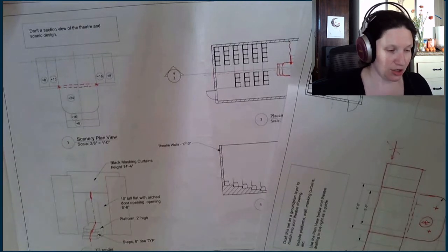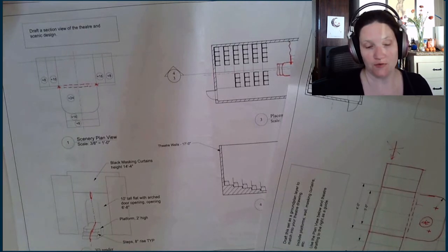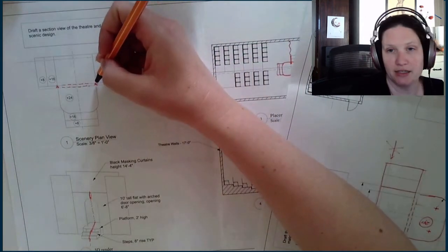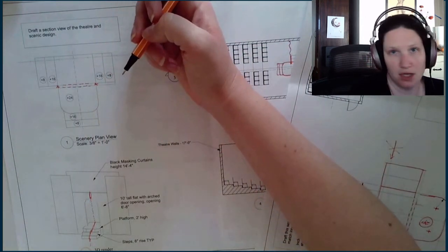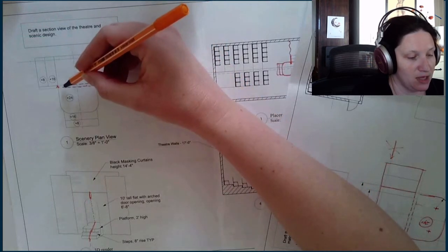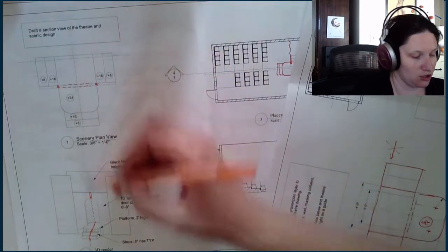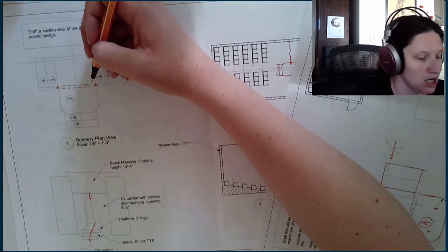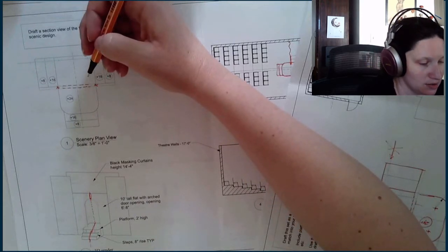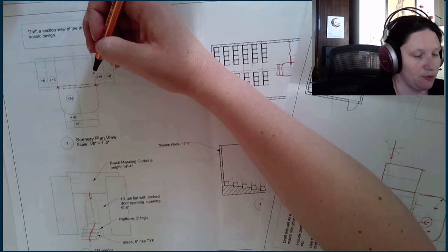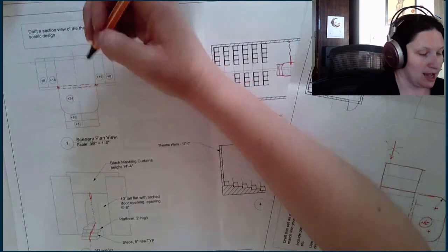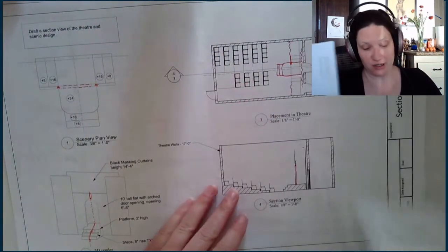Other things that are incorrect that you would want to change from this sketch I've given you: these lines that you see I've drawn a little X on, they would not exist. And then this opening for this archway would have dashed lines as indicated, okay? So those are two things that would be different from the drawing that I've given you in your final drawing.